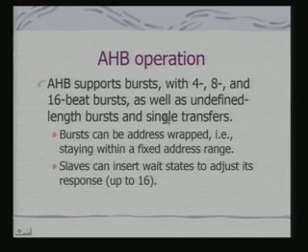It supports bursts. Bursts can be in terms of 4, 8 and even 16 word transfers at one go. And these bursts can be address wrapped, that is, the burst stays within a fixed address range, and slaves can insert wait states to adjust their response.